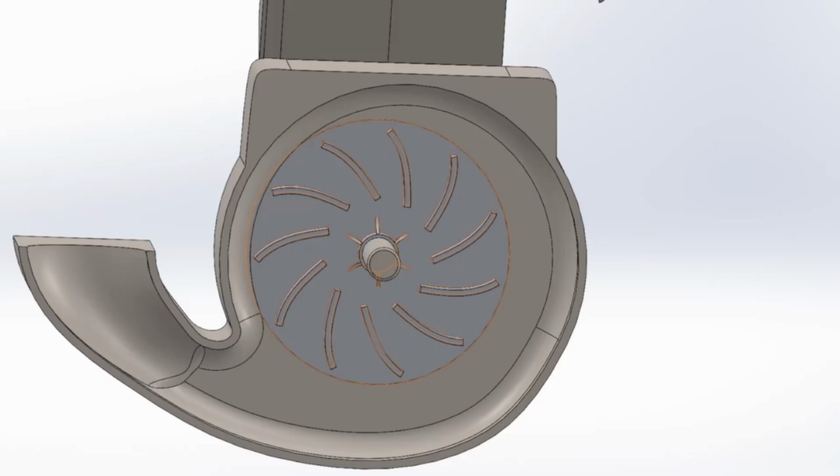as it moves outward. As the fluid moves from the center of the pump to the outer edge, its pressure increases and its velocity also increases. This might not be so intuitive because due to Bernoulli's principle, we would assume that as pressure increases, velocity would decrease. However, we must remember the fluid is not moving in a single streamline. Once this fluid gets to the edge of the pump, it will have high velocity and high pressure, and then it leaves the pump at the exit on the left side.